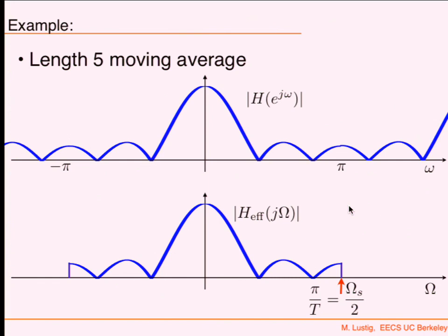LTI. So I can go and sample my signal at 44 kilohertz, downsample by 5, do processing, and reconstruct it as if it was 5 kilohertz sampled. If that was true, then I'm good. If I would reconstruct it as 44.1 kilohertz sampled, then my voice is going to be really, really high, and it's going to sound like a mouse, right? Okay, but that's the difference.